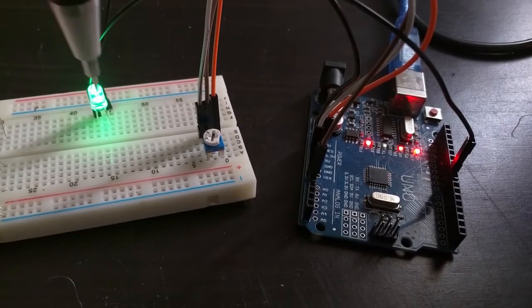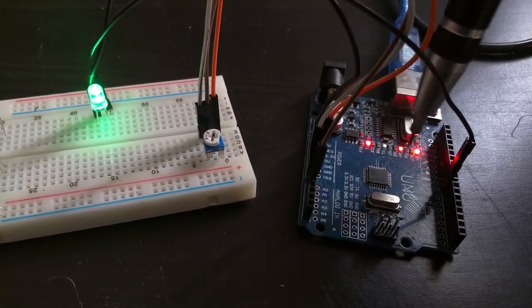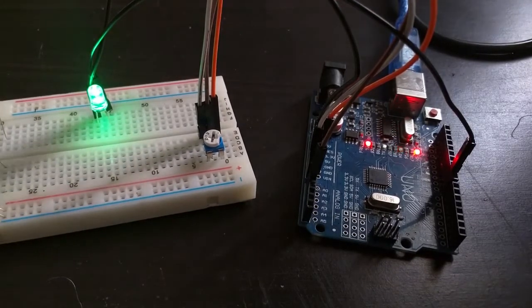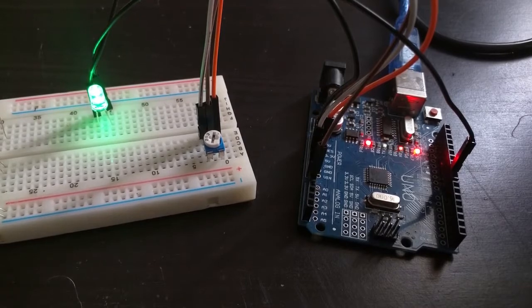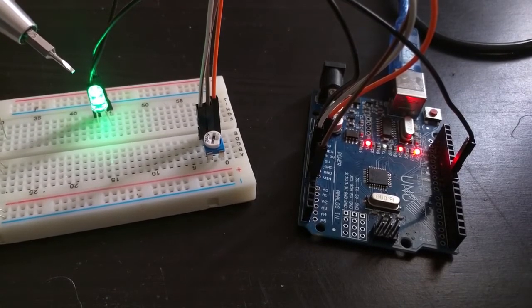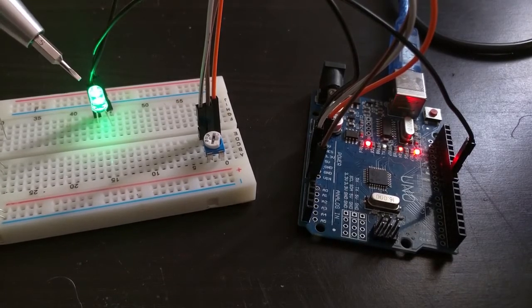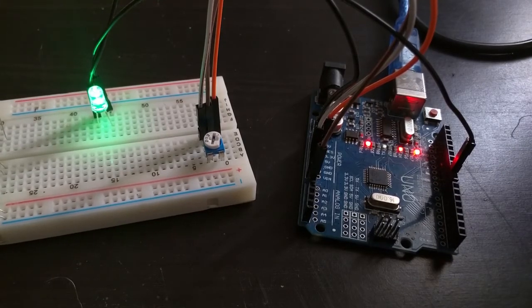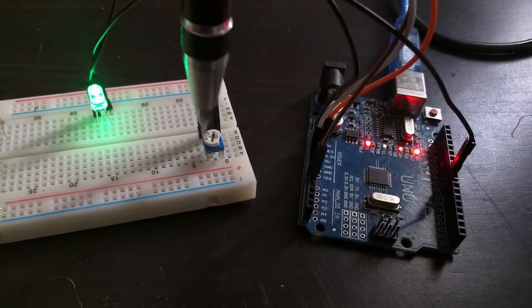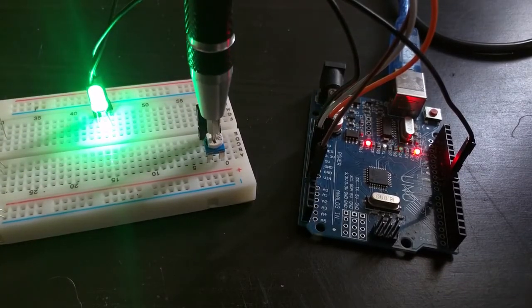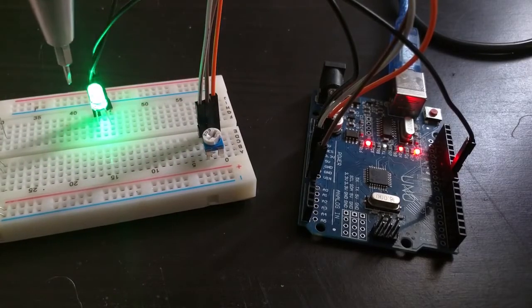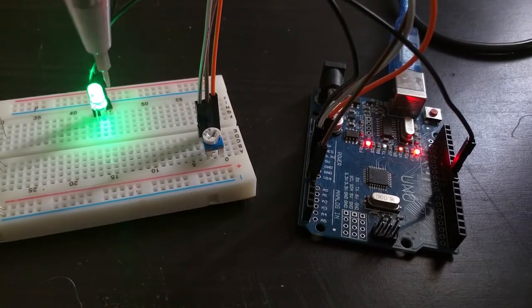So just note that this LED is not being dimmed in an analog fashion with a variable resistor. It's dimming through pulse width modulation through this microcontroller, which is sending those on and off pulses to the LED. It's just that the on and off pulses are so fast, within the kilohertz range, meaning it's pulsing at thousands of times per second. So the pulses are not visible to the human eye, but the effect of the dimming and brightening of the LED is visible, because when it's dimmer, the LED is off more of the time, and when it's brighter, it's on more of the time. So in effect, it's changing the average voltage to that LED.